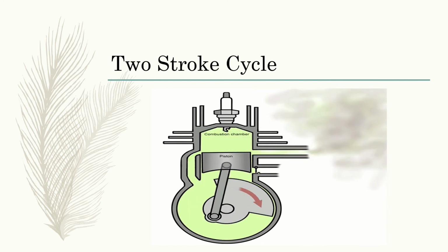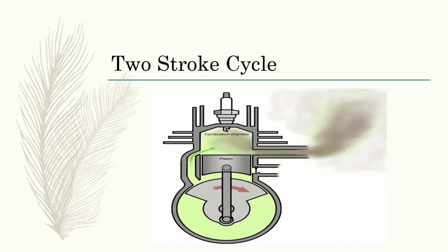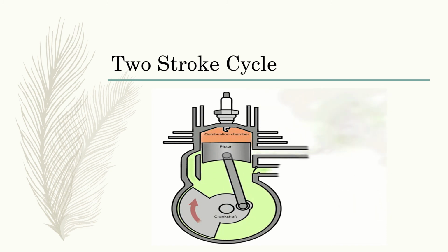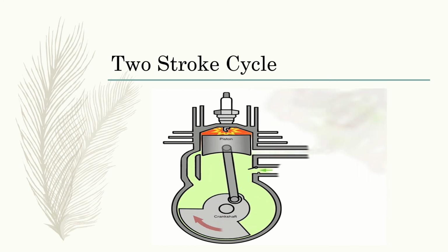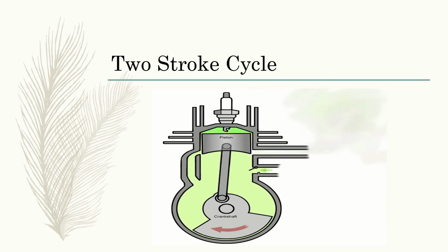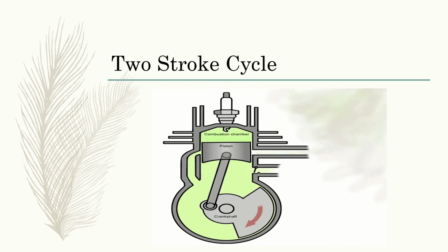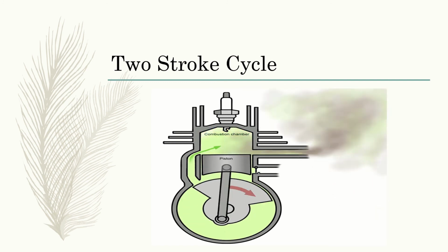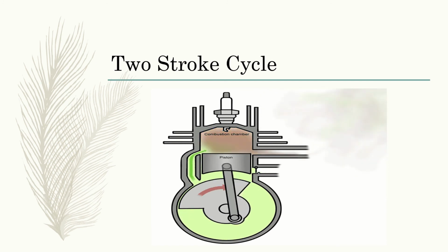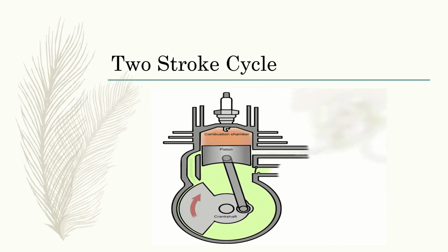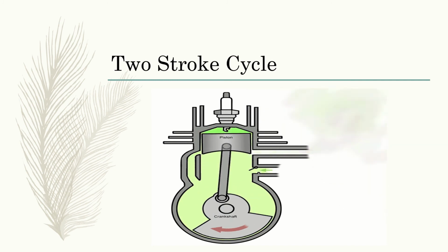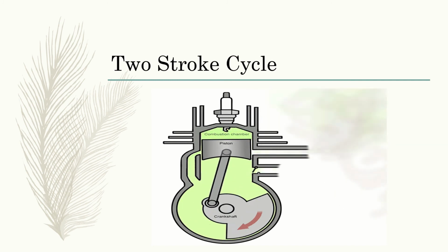Another key difference between engine designs is that two-stroke engines are less expensive to build, lighter, and offer a higher power-to-weight ratio than four-stroke engines. For these reasons, two-stroke engines are ideal in handheld applications like chainsaws, string trimmers, and backpack blowers. Two-stroke engines are also easier to start in cold temperatures.